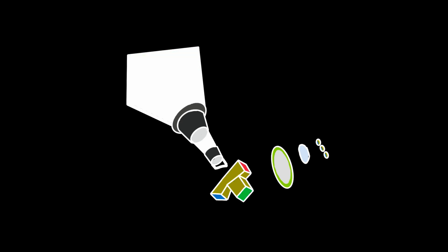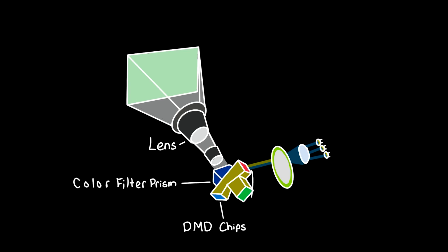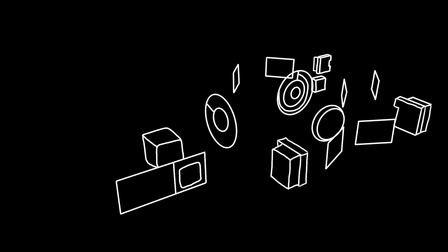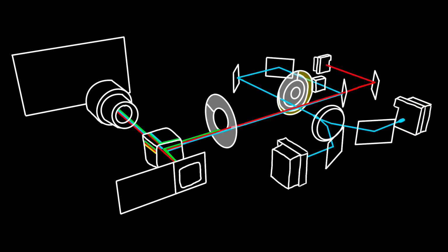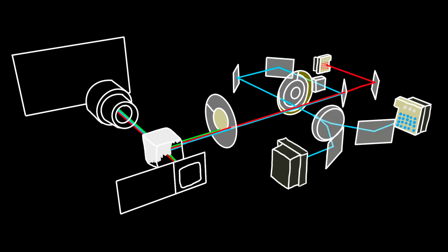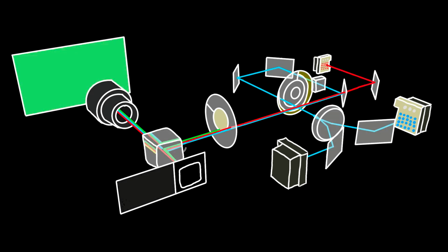RGB laser projectors, also called direct laser projectors, use three individual colored lasers. This allows for a wider color gamut. They can reproduce DCI-P3 or Rec. 2020 color gamuts without a color filter. RGB lasers are considered to be the best projector light source available. However, using this technology is very expensive as they tend to be physically larger than other projectors and are currently best suited for installations and cinema.